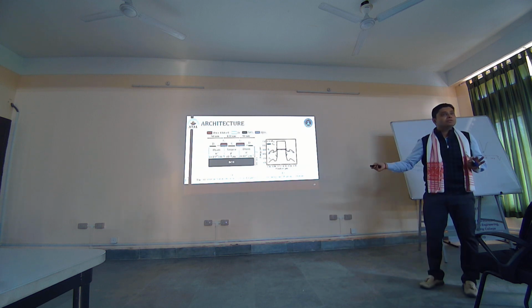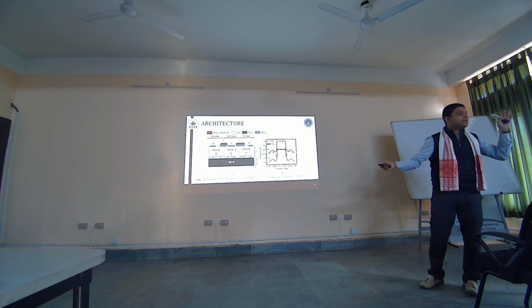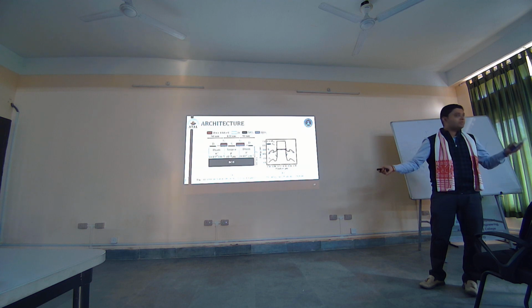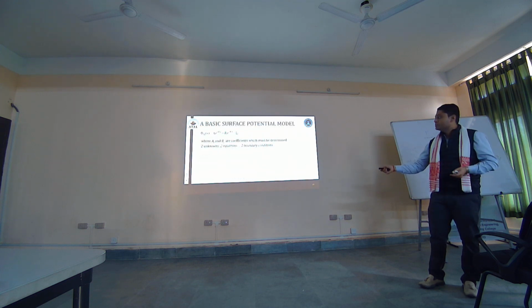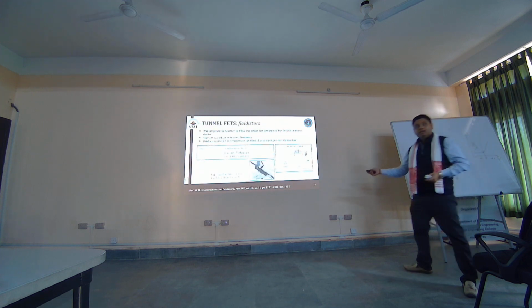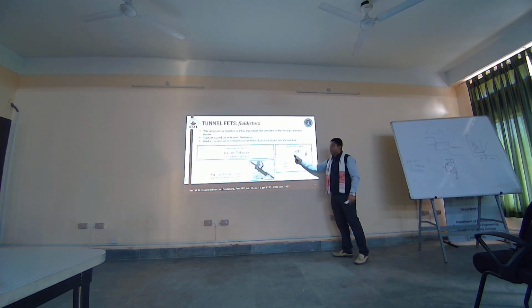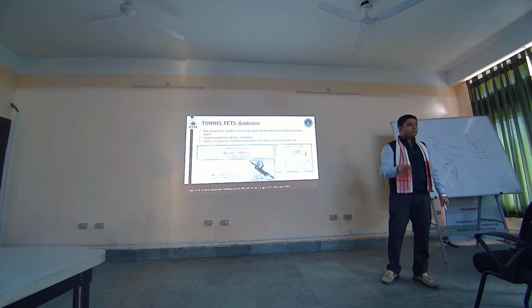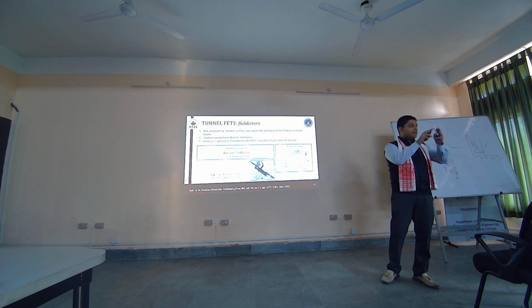Are you getting my point? This was due to the technology not being developed, or the die areas being very huge, so they also had to worry about breakdown voltages. So despite the fact that Schweitzer already gave a PN junction based TFET, people actually took up PIN TFET as the basis for your conventional TFET, because they had to think about breakdown voltage, and an intrinsic layer in between gave a very good breakdown voltage for the device.